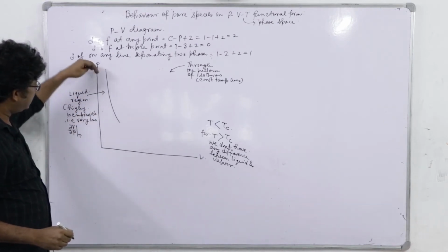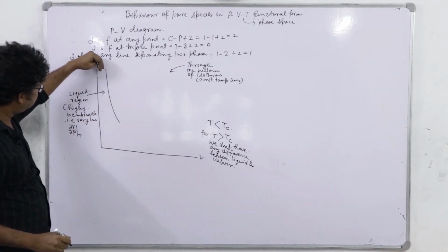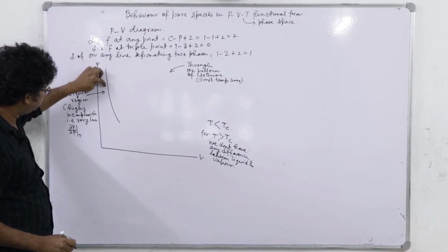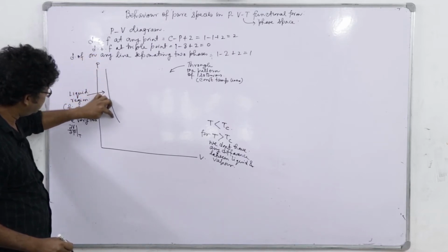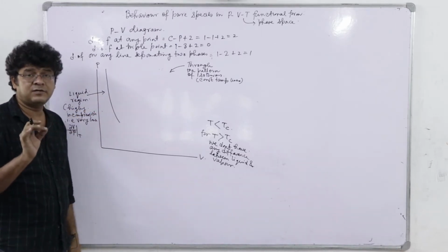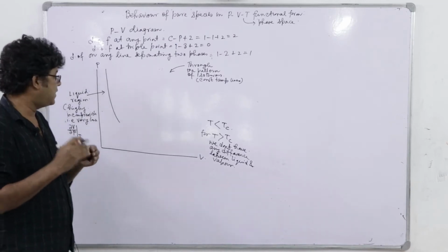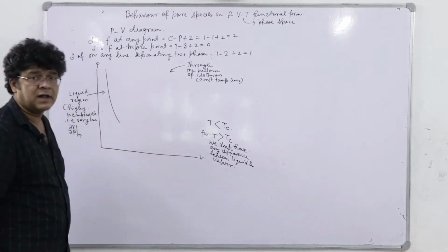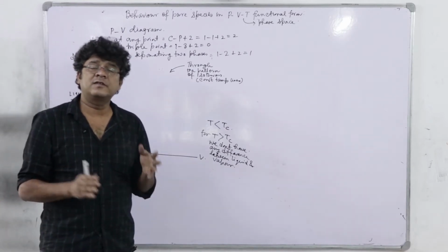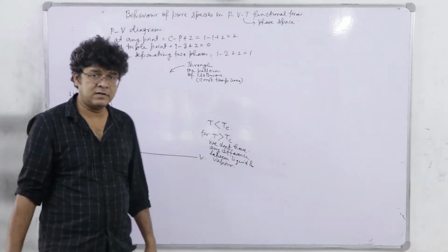Now, once the liquid, see it is at constant temperature and we start from a very high pressure, we are reducing the pressure. So, volume slightly increases and at a certain point it will be saturated. Once it is saturated, further if you try to reduce the pressure, there will be no pressure reduction unless there is a phase change, right.